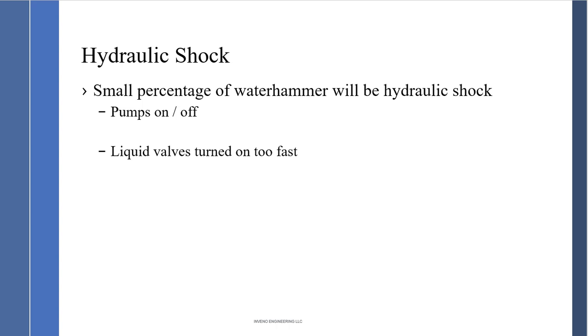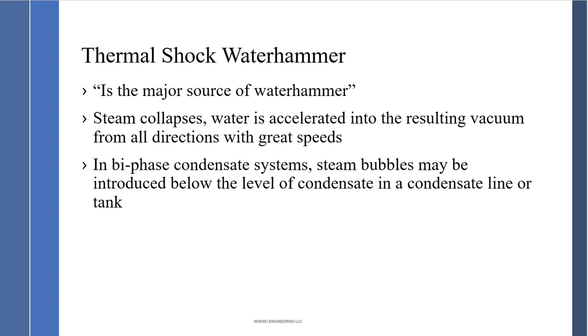Hydraulic shock. A small percentage of Waterhammer, not too significant, will be hydraulic shock, like condensate pumps turning on and off, or liquid valves turned on too fast. Very, very small percentage. The major source of Waterhammer is thermal shock. Steam collapses, and water is accelerated into the resulting vacuum from all directions with great speed.